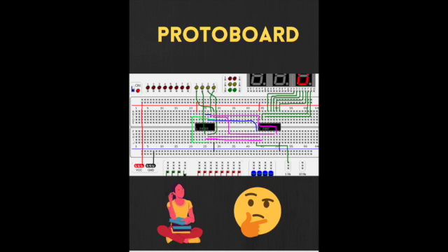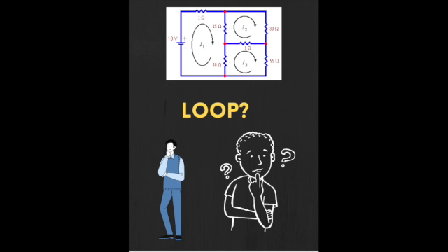In this practice, we use a new element, which is the protoboard. A protoboard is a plate where you can do proofs. It is made to insert electronic elements and cables in order to form a circuit. Protoboards have little holes that are connected between them. The protoboard has to be connected to a battery with a positive and a negative terminal. In the upper and the lower parts of the board, we have connection strips, and all the holes are connected to the same strip.